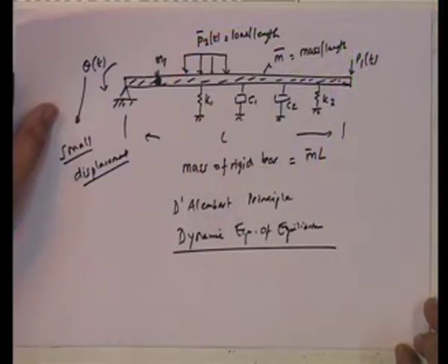So, then theta becomes a specific value, theta at time t. Take the displacement pattern and see what are the forces that are acting on the body. Okay. And then take an equilibrium, write down an equation of equilibrium. So, these are the steps that we are going to follow. Okay. And if we follow those, so let us look at this.